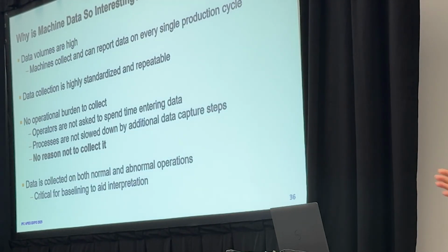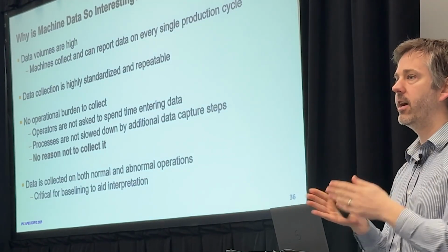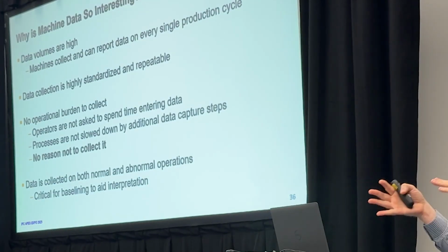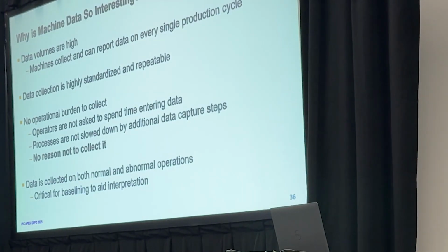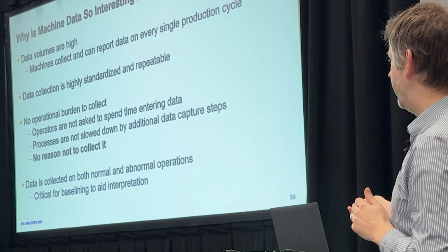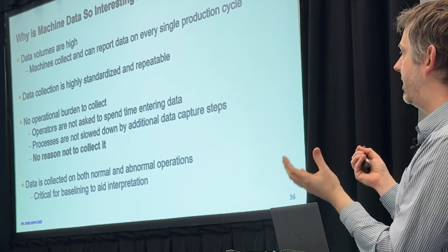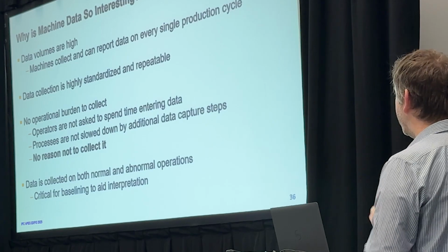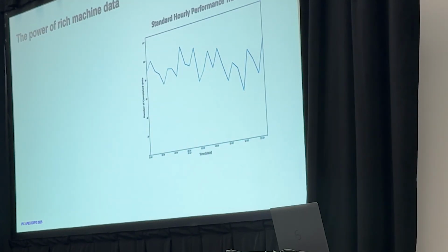If you have a normal mass production scenario where maybe my yield is 99%, I get 99 passes for every one failure. It means I'm building up a nice big picture of, okay, what does pass look like? And that can help analyze that data to understand, okay, what are subtle signs of not quite failure, but getting to failure? So what do the tails of that distribution look like on the pass side? That's one of the reasons why it's particularly interesting. And I like to highlight this with an example.